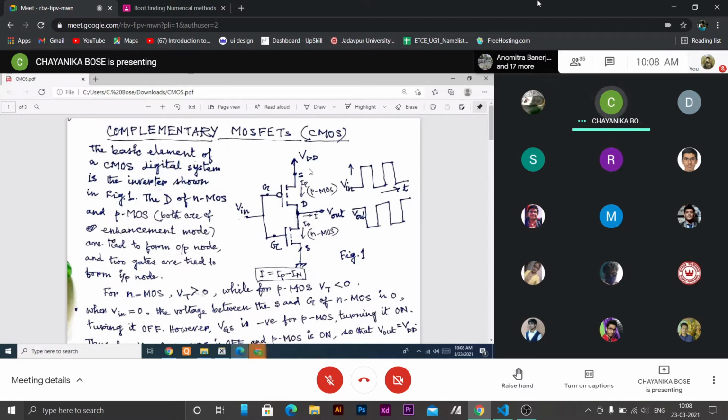The number of MOS that can be accommodated will increase as their size becomes smaller. MOS আমরা দেখেছি already Z/L ratio appears, so we reduce the size dimensions, keeping the ratio the same, so their current will remain the same. So we will pack them in a closer way within an IC. But in that case, since they are densely packed, power dissipation becomes a factor.